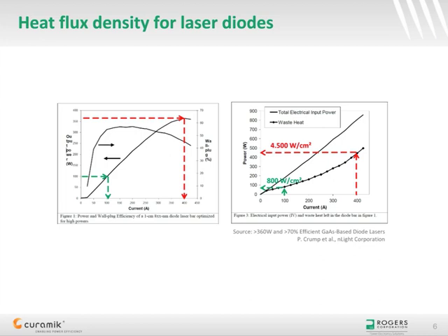Figure 1 shows the optical output power and power conversion efficiency for a 1 cm laser bar mounted on a water-cooled microchannel heatsink. As indicated here, a peak power of 364 watts can be achieved while holding the water temperature at 6 degrees C. But the best power conversion efficiency is achieved for 100 watts of output power, as the performance of diode laser material degrades at higher temperature.